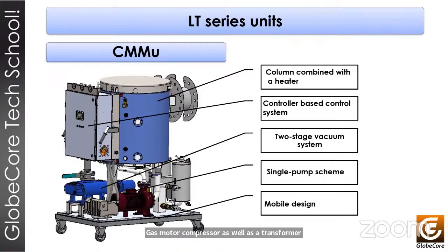The unit can be used for purifying contaminated oils from water, free and dissolved gases, for heating and dehydration of oil-filled electrical devices with transformer oil using the thermal vacuum dehydration method, and for removing solid impurities with the use of high-efficiency filter elements also. The unit is used by installation, repair, and operation organizations involved in oil processing and purification.